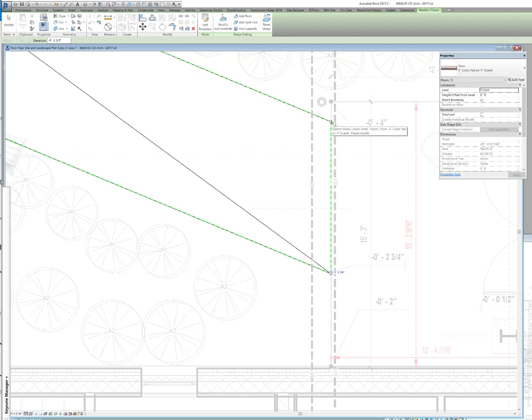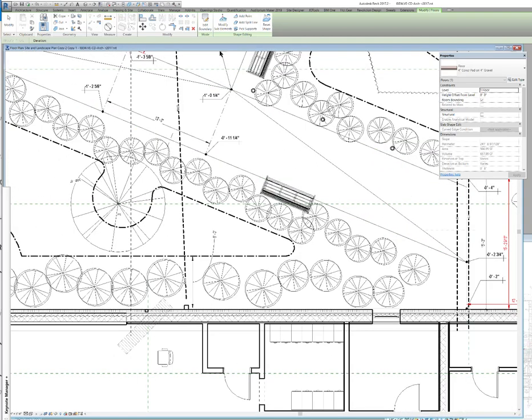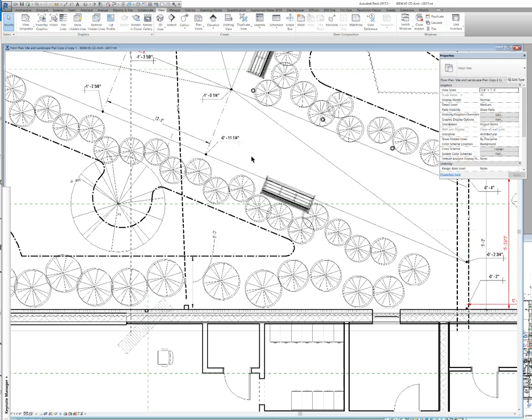I want this to be 1/8 of an inch below that. I'm sorry, 1/8 of an inch to the foot, 1 inch. So this should be negative 3 3/4. Good. Okay, so that's set. And to back out of this mode, you just hit escape and you don't lose everything. It just backs you out.